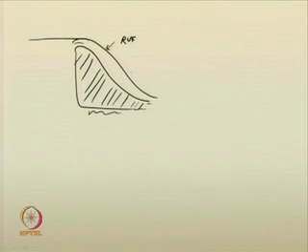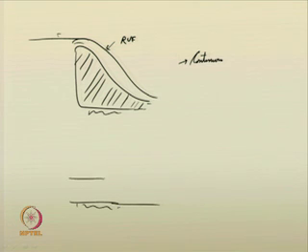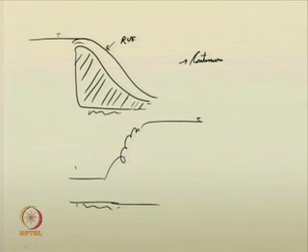Still, due to the rapid change in the profile, the water surface is not getting discontinuous; it is still continuous. However, in jumps, if you recall them, you have disjointed water surface profiles here. So, in rapidly varied flow you can have both continuous water surface profiles or discontinuous water surface profiles. A classic example of discontinuous water surface profile rapidly varied flow is the hydraulic jump.